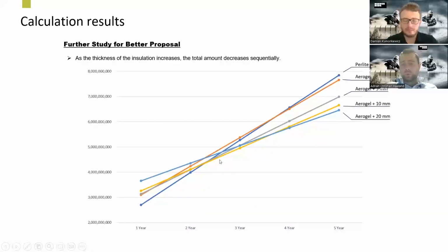Here you can see an example for one piece of equipment where yes, you might have a little bit higher insulation thickness than the performance that was historically. So instead of using aerogel to match the performance of the perlite, so thinner thickness, we choose to put on a little bit more aerogel so that we can actually, for one, reuse the same cladding because the dimension is actually the same. So we contribute to the reusability of the cladding system. But we also see that on a short time horizon as 5 years, even after 5 years, we have paid back the extra capex expense up front.